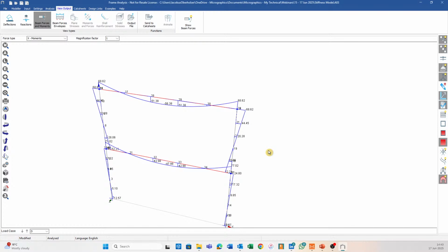I would say again that in the event that you have a connection that doesn't fall within the normal spectrum, due to geometric constraints or just due to structure geometry, I would really recommend that you actually do run a stiffness analysis and check whether your design of the connection, or just the look of the connection, is actually tying in with what you've set up in your global model, right?